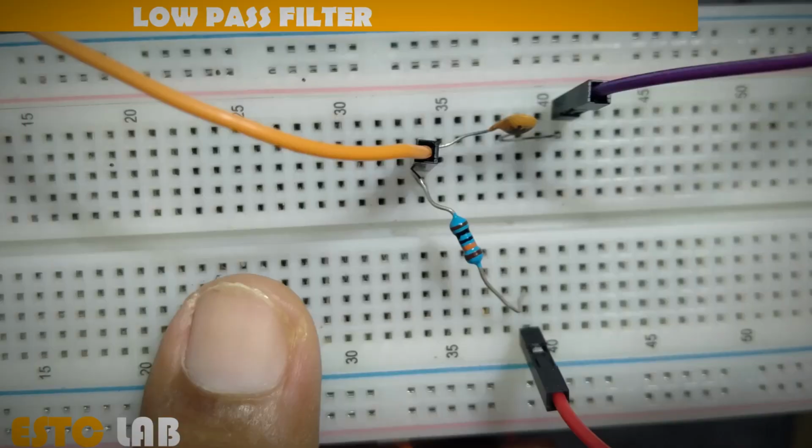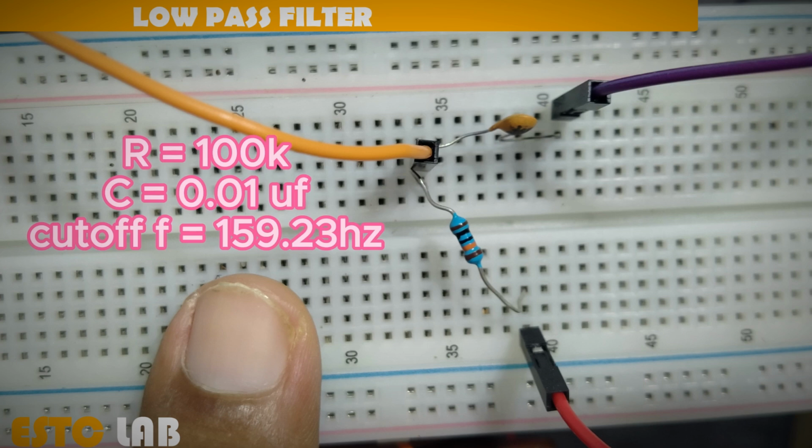So this is the circuit for the low pass filter. The red wire is going to one side of a resistor, orange is for the output, and the violet wire is the ground. For the experiment of both low pass and high pass filter, we are using a resistor of 100k ohms, meaning 100,000 ohms, and a capacitor of 0.01 microfarad. The R and C are such that the cutoff frequency is equal to 159.23 Hz, which we can say is about 160 Hz.